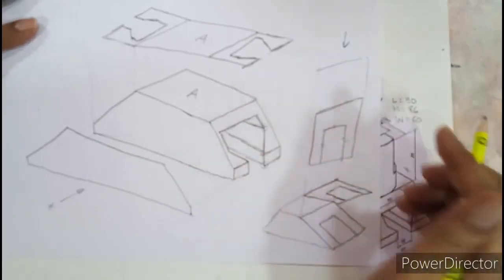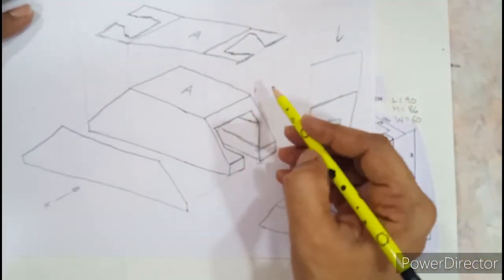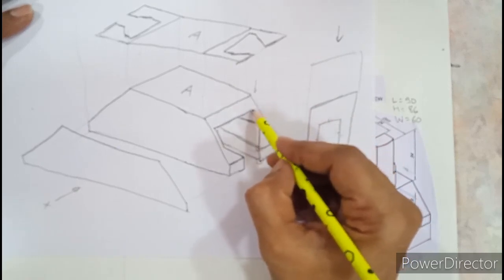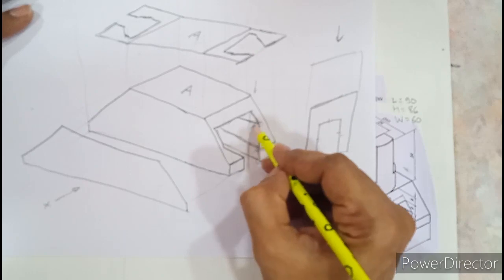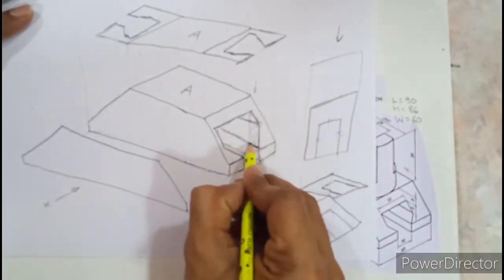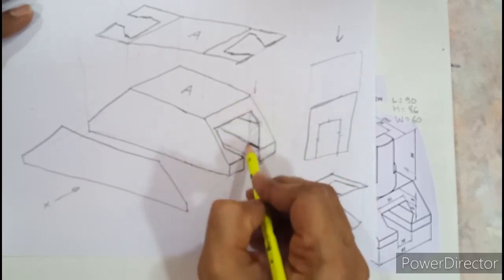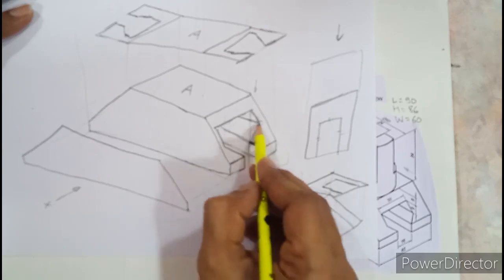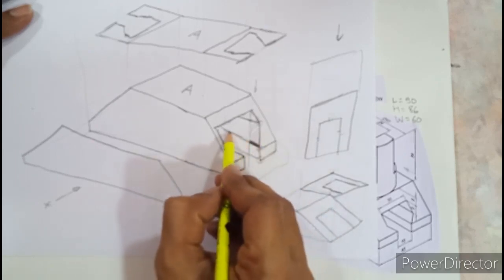Now very important thing we are going to discuss here. What is that? So in the top view, orthographic is nothing but projecting parallel rays of light. So when you project parallel rays of light and when you extend this down, some part of this surface will be seen. In other words, you can see this edge up to what level, up to a ray which is perpendicular with the ground. So you can see this edge, what I have shown by dark. You cannot see the remaining edge.